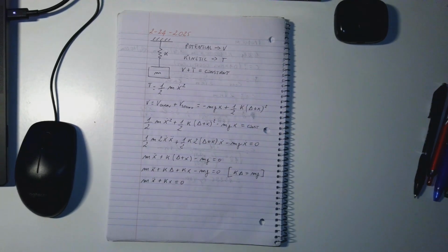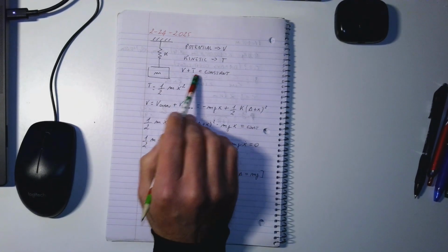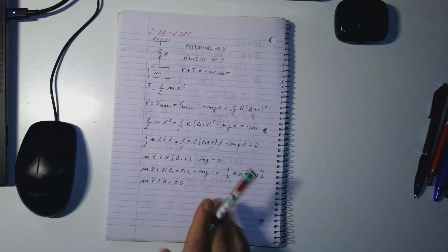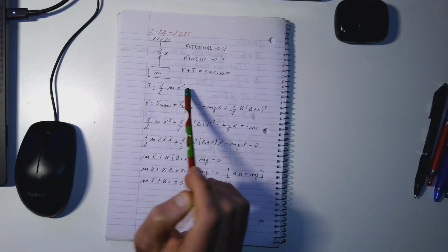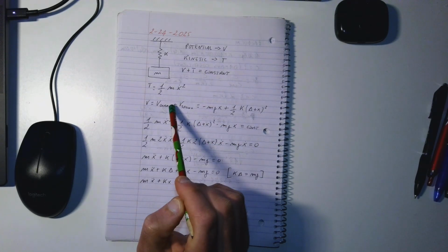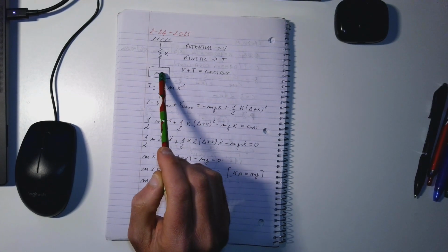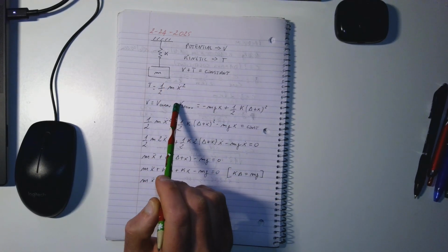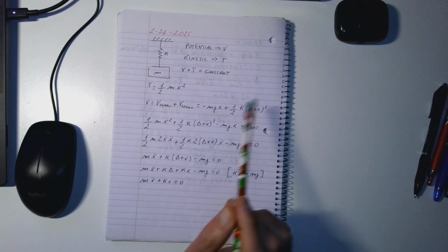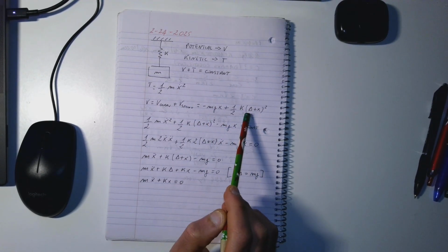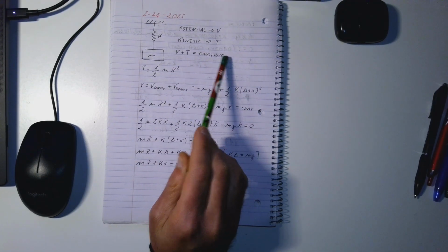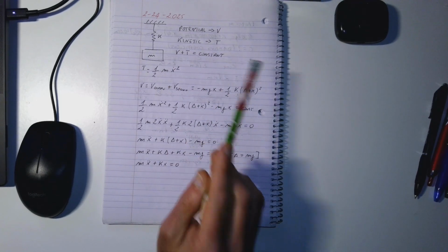And if this is the case, we are in a situation in which the summation of potential and kinetic energy is constant. So what we need to do is simply look at the kinetic energy of the system and the potential energy of the system, and put them together. In this case, the kinetic energy is related to the velocity, the potential energy is related to both the gravitational force and the force of the spring, so we can include both contributions, and then we take these three terms and plug them into this equation where we have V plus T equal to constant.